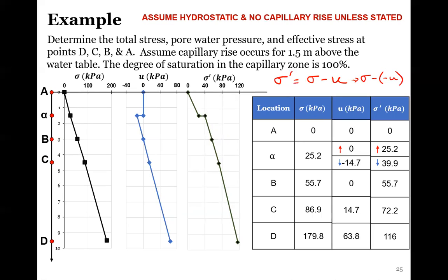All right, sorry I'm going through these kind of fast. Is the A the new top of the water? Like 1.5 here. This alpha right here, that A? The top. No, so this is at 0 here. This is the ground surface. So the groundwater table is still here at B. But now we have, this is the zone of suction. So this is actually 0. So that's why we have the negative. Oh, okay. I thought it was like above the ground. Okay, no, yeah. There's no ponding, there's no flooding or anything.